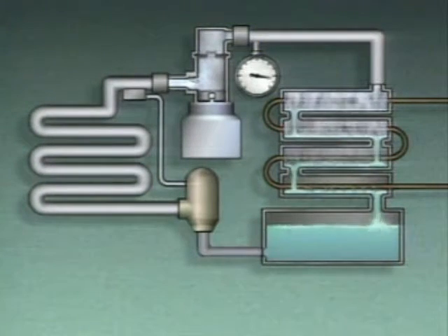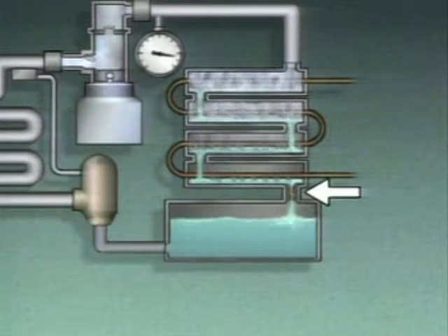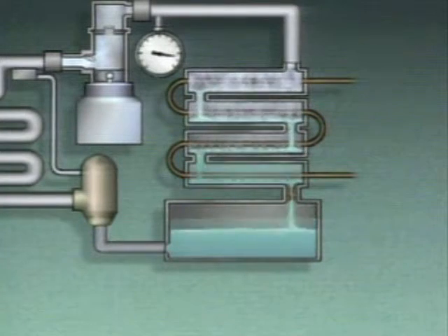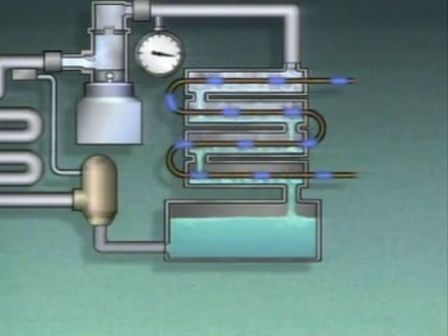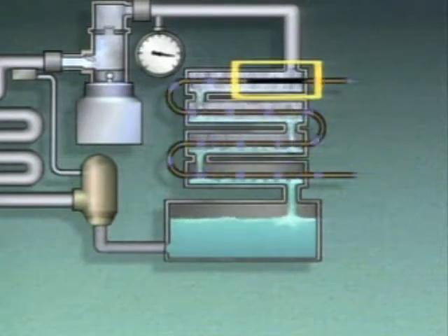There are a number of reasons why discharge pressure can build up from a reduction in the condensing rate. For example, a blockage between the condenser and the receiver will back up the refrigerant. This reduces the amount of condensing that occurs and increases pressure. Another cause of a reduced condensing rate is a decrease in the flow of cooling water. For instance, a blockage in the cooling water system could reduce the flow of water through the condenser and reduce the amount of refrigerant that can be condensed.